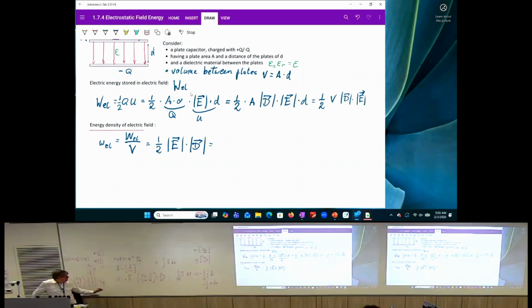And maybe the flux density is also quite nice because it gives you this aspect that it is really a quantity that is taken over square meter, over an area, while the electric field is a quantity over meter. Always you integrate the electric field over a path. The flux you integrate always over an area.